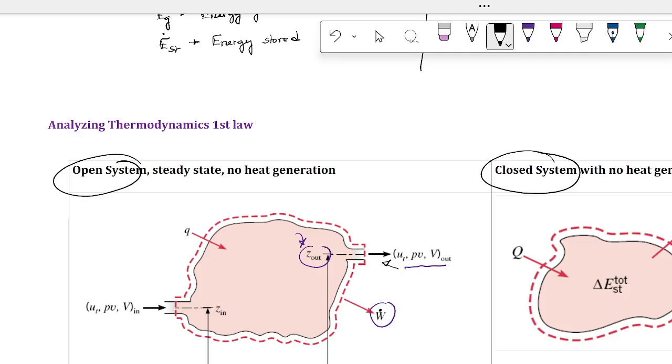What if those are not balanced? That means say more water is coming, less water is draining. That means the water level is going to keep rising. That is the energy storage happening over the time. Not the generation. Energy storage happening over the time. Everybody got that? So with time, if the amount of water coming and the amount of water going is the same, then it's the mass balance. That was the mass balance thing. I'm doing an analogous thing here with the energy balance.